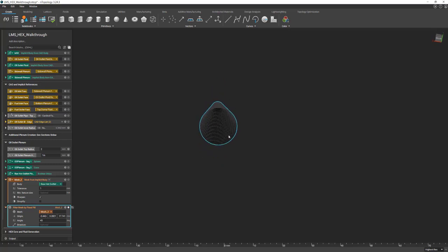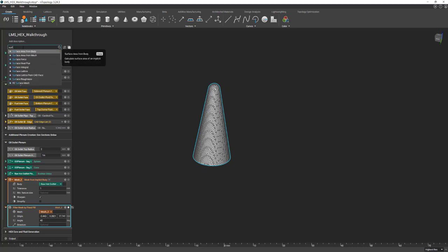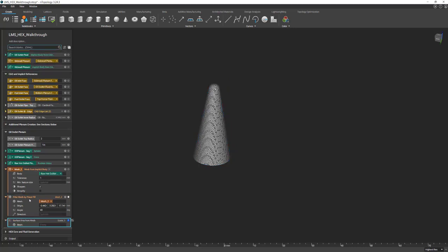We've in fact captured just the top half of the cone, or the top section of the cone. Might capture a little bit more, so we would turn this to 40 to ensure that we're only capturing this section. Then what I can do is surface area for mesh, drag this into here, and see that I have an exit area of 700 millimeters squared.